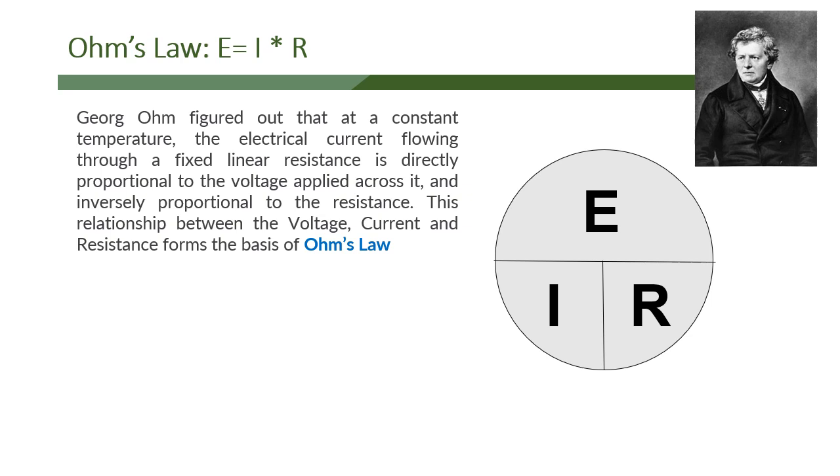So remember we were talking before about resistors and that they resist the flow of current and that there are different types of resistors, and you can calculate resistors in series, summing all the resistors in that series pathway. We can calculate the total resistance of parallel resistances using the formula we showed you. And then if we have a complex network with series and parallel resistances, we're going to do the parallel resistances first, replace them with an equivalent one resistor, so we end up with a set of series resistances that we can then add up to have the total resistance. So that's basically what we've covered with resistors up to this point.